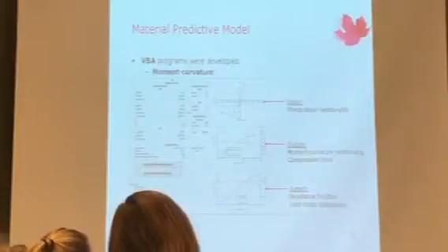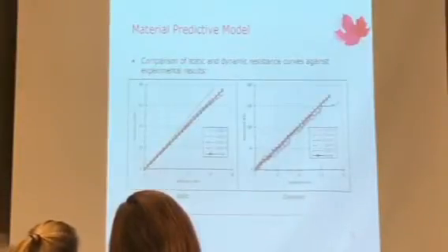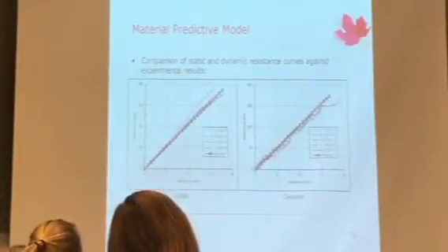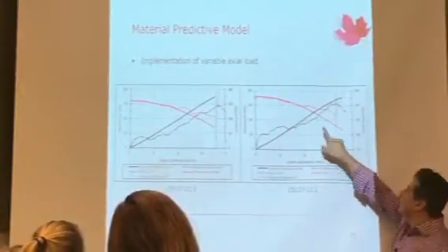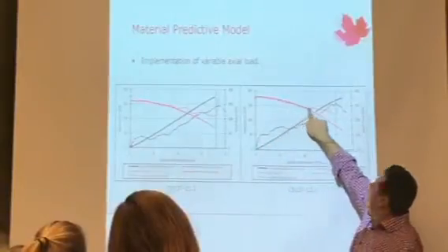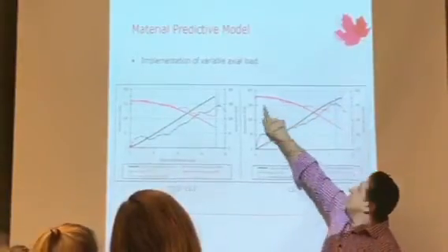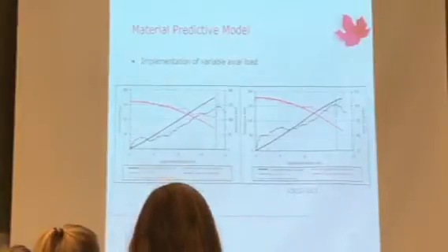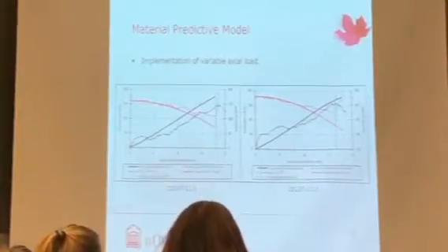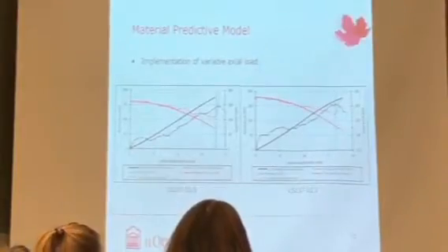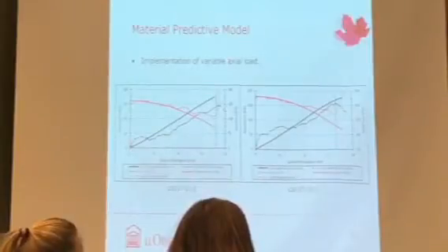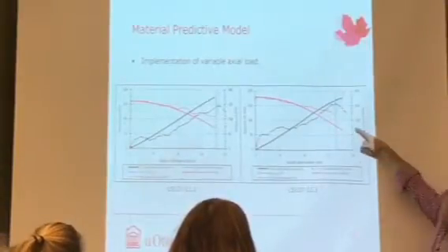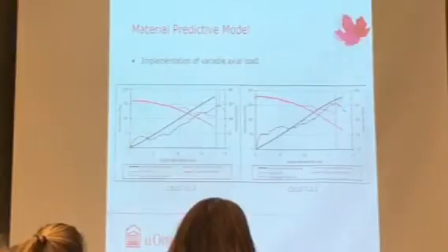And we can match static test and dynamic test fairly well. We can also match with our analysis that descending, so this is the actual axial load, and this is our theoretical axial load that's shown there. Pretty good in the beginning until we reach a certain point where I think we get a little bit of clamping at the end, so that the axial load increases. You see it in this case, how it kind of jumps up. And so beyond that point, of course, we have too much clamping, and it's not the actual axial load that we're dealing with.